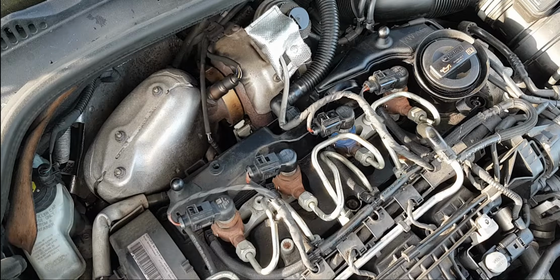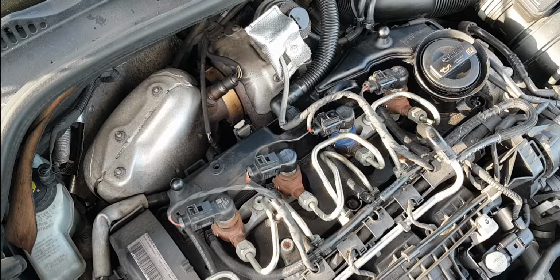So yeah, it might take a few turns, but let's hope that there's not too much air in the system and it starts. Before I start the engine, I'm going to turn the ignition on and off maybe 3 or 4 or 5 times just to be sure, and then eventually I'm going to crank the engine to start it. So remember, just turn the fuel pump on and off a few times, and then after that try and start your engine.